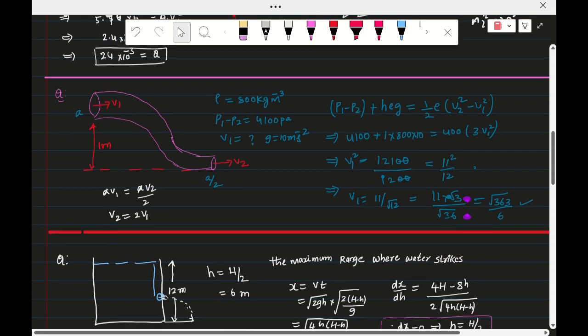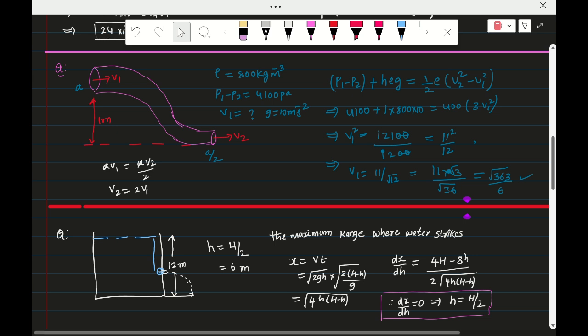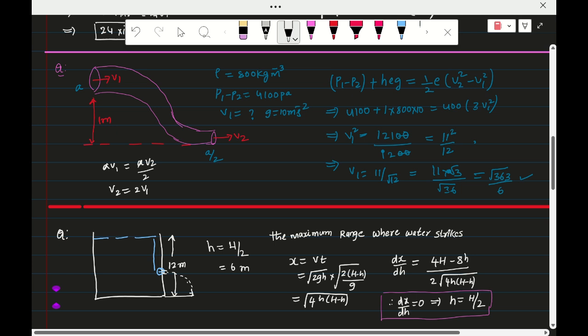Now the next model of problem. Here in this problem you can see there are two cross sections of flow, the unsteady flow. V1 and V2 are different, which means non-uniform and unsteady also. Now the pressures also differ, which is why it is unsteady. Steady means dp by dt is equal to 0. Already in the flow chapter I explained what types of flow there are. So it is unsteady flow and non-uniform also.